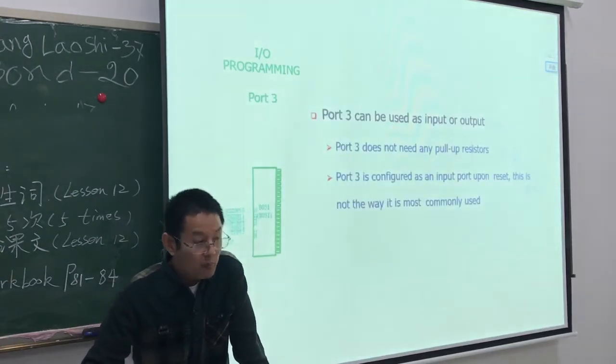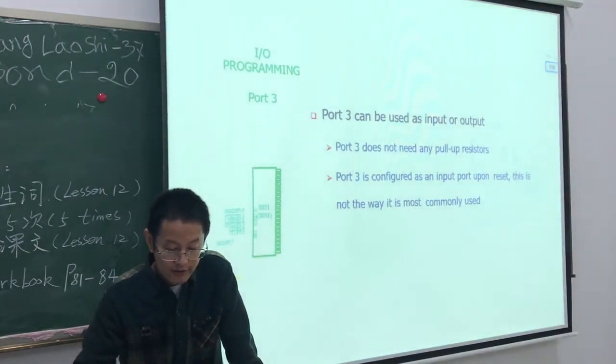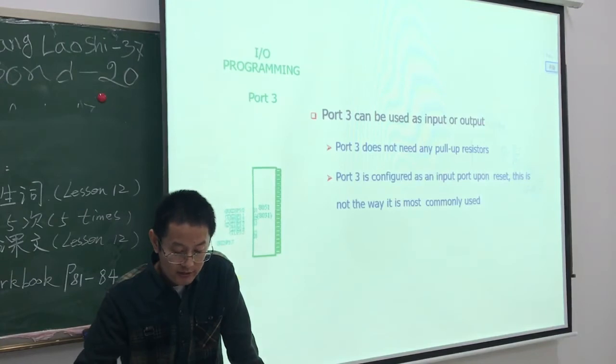Port 3. Port 3 can be used as input or output. Port 3 does not need any pull-up resistor. Port 3 is configured as an input port upon reset.